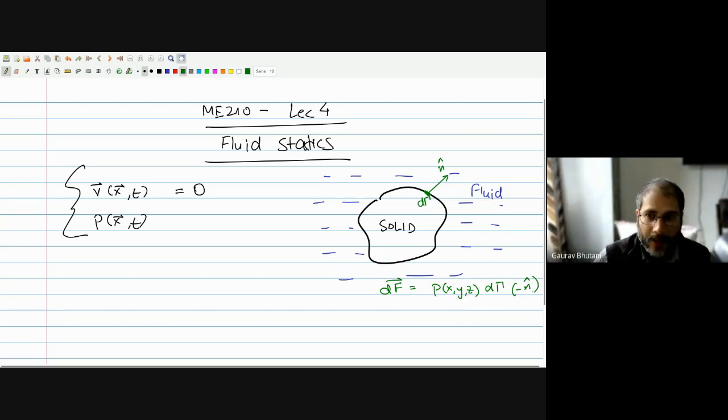So this is typically what we need the pressure for, that is to calculate force. And in case you want to find out the total force F acting on the solid body because of all the surface forces due to pressure, it is simply the integral of dF over the complete area gamma of the solid surface area. Right. So that's quite intuitive anyways. It's just a bit of mathematics here, but otherwise the ideas are all clear to us.